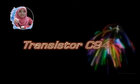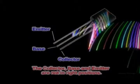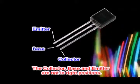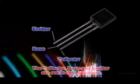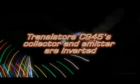Transistor C945 became our second problem. From our project, we had wrongly understood the function and the connection of the transistor. The collector, base and emitter were not in the right position. This kind of transistor is slightly different from other transistors. Transistor C945's collector and emitter are inverted.